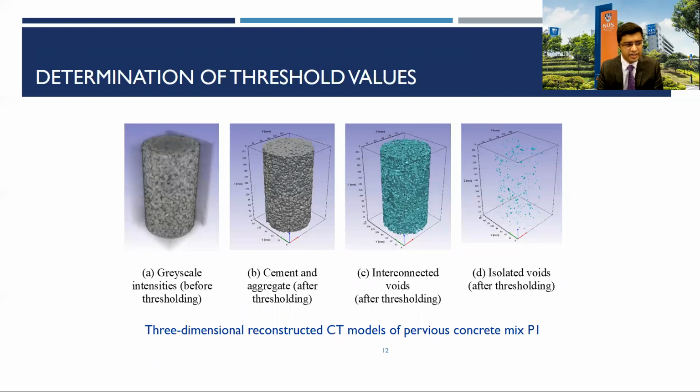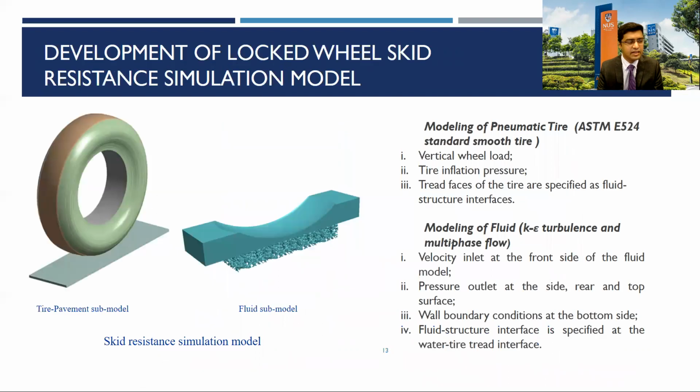After the threshold values are obtained, we can obtain the 3-dimensional reconstructed CT scan models for various phases like the cement and aggregate phase, interconnected void phase, and isolated phase. Next is the development of the locked wheel skid resistance simulation model.